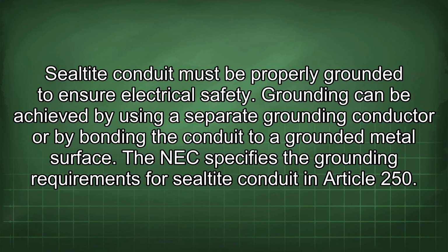Sealtite conduit must be properly grounded to ensure electrical safety. Grounding can be achieved by using a separate grounding conductor or by bonding the conduit to a grounded metal surface. The NEC specifies the grounding requirements for Sealtite conduit in Article 250.